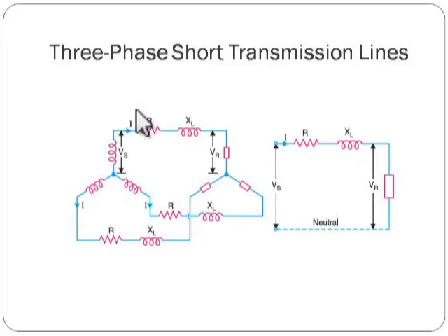Whatever we have in this star connection is in the distributed form, so I have to conveniently modify this circuit into the lumped form. That is, I times R and X_L, and connected by load in between your line and neutral, so we may get our phase values. So at my sending end side and the receiving end side, my circuit becomes more and more simple here.